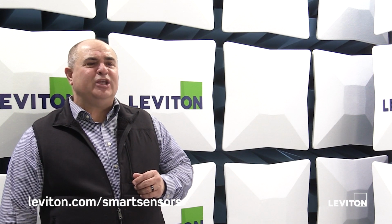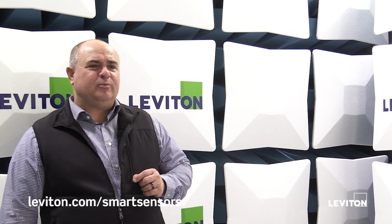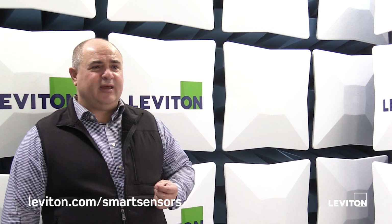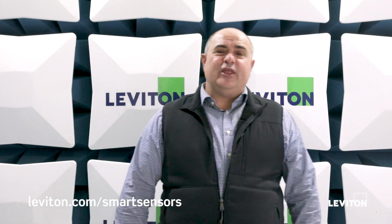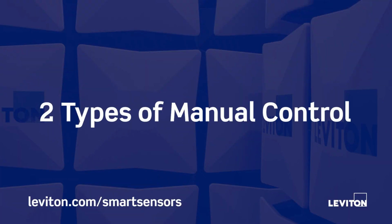Now, one of the things that we really need to make sure that we understand is that every fixture within the facility, again with Title 24, you do have an ability to have 0.1 watts per square foot that is not controlled by a manual switch, but every light in the facility needs to have the ability to be turned on and off. Now, understand, because it's understood that there are some areas within the facility where that might be a safety concern, the code also allows and brings attention to the fact that there are two types of manual control.